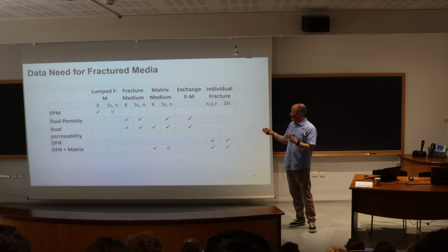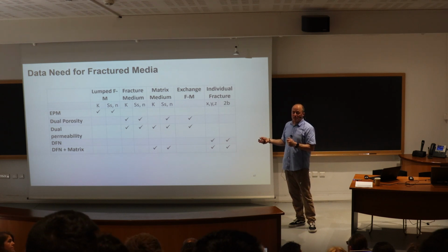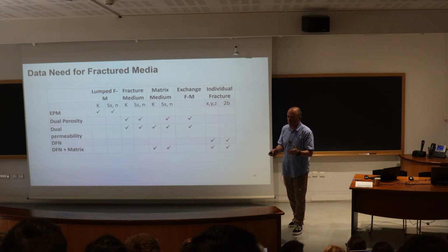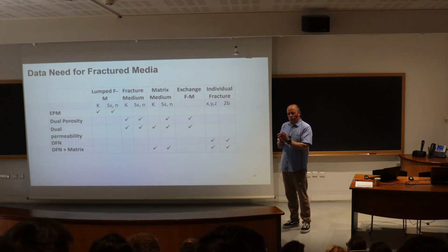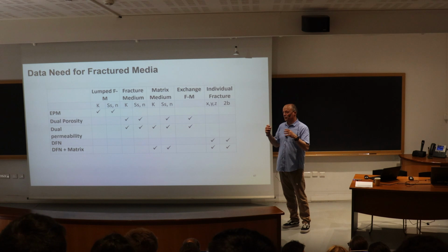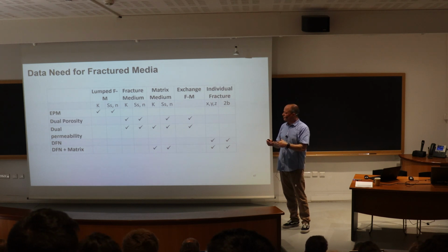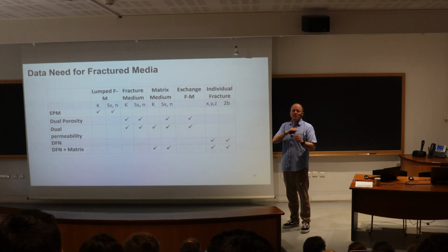So additional information is required for these individual fractures, but there can be a combination. I think the more pragmatic approach that you will certainly be seeing, at least from Philippe Davy, is that if you can quantify the smaller scale features in your systems, smaller scale fractures, you will use some upscaling approach to get either equivalent porous medium properties or dual porosity properties to put in your model, and the larger scale features you might want to represent as individual fractures.